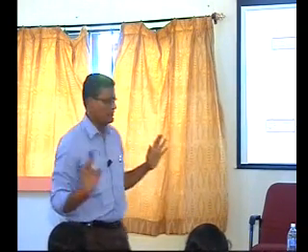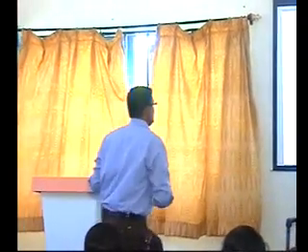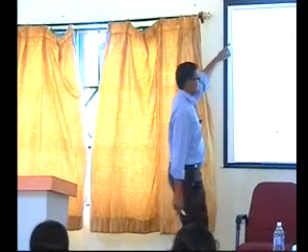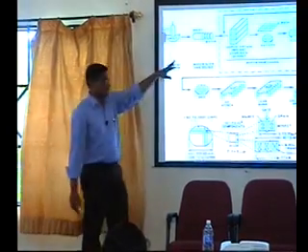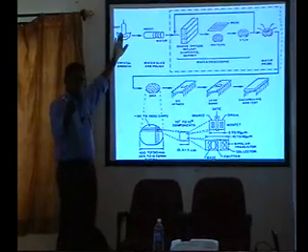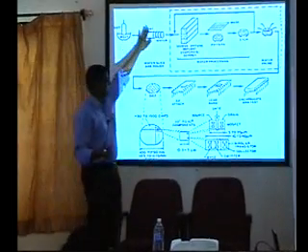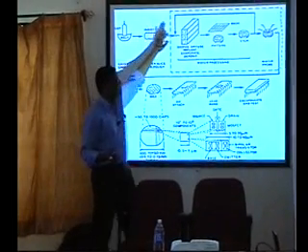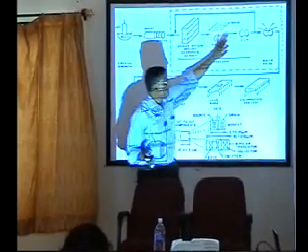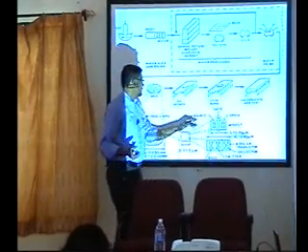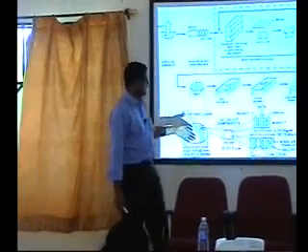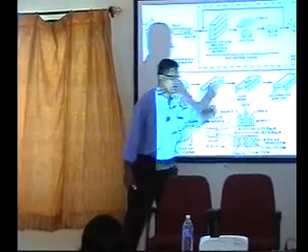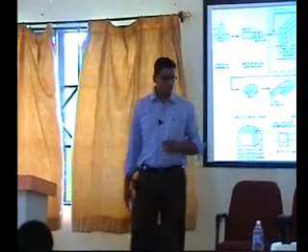Next. So these are the things I told over the last half an hour or so. I am summarizing here. I take this molten silicon, and the molten silicon is made into ingots. Then it is etched, polished, and then you go for photolithography, and finally you get it as a product or in an IC form. Okay? Next slide.